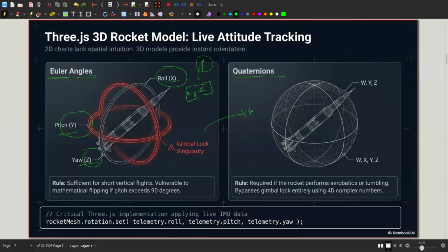So that is how the rocket can see itself. It sends you three values, the roll, pitch, yaw, and just by using three values, you design a system. Basically, using quaternions, there is a formula, and this is the critical implementation, a one-liner implementation.